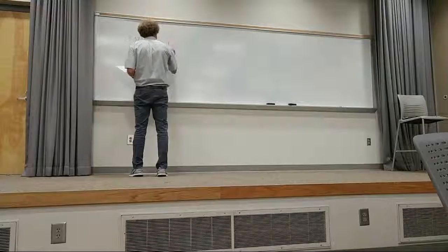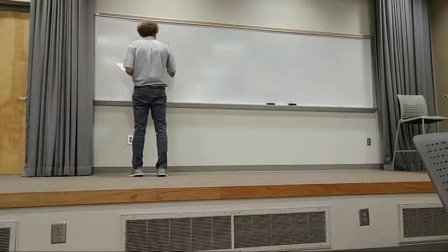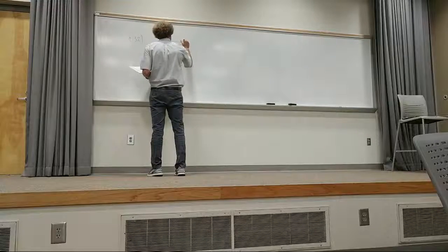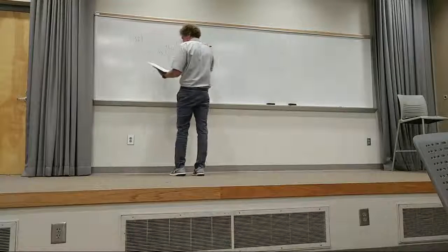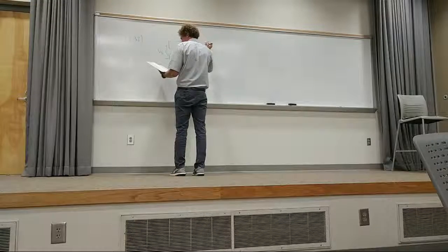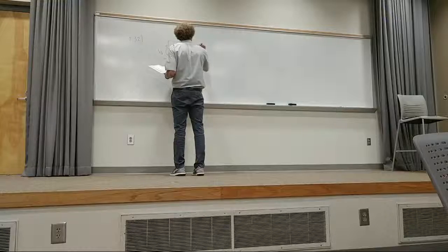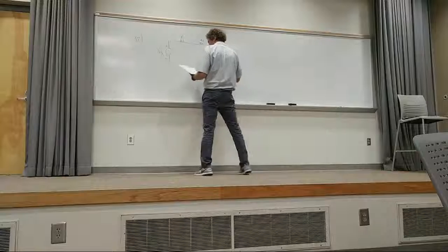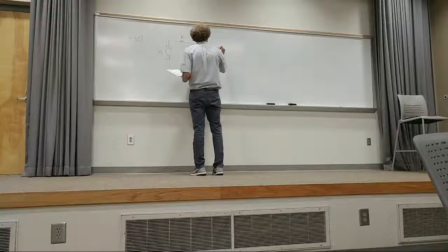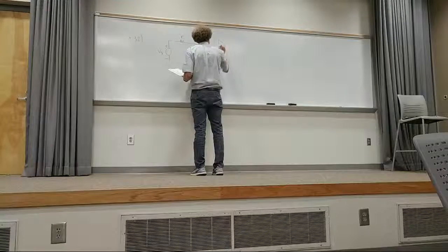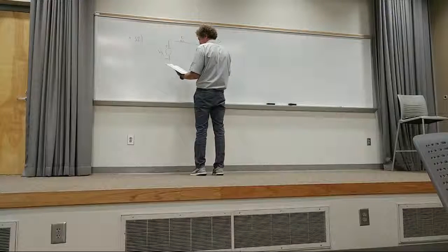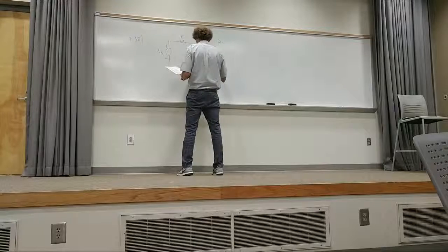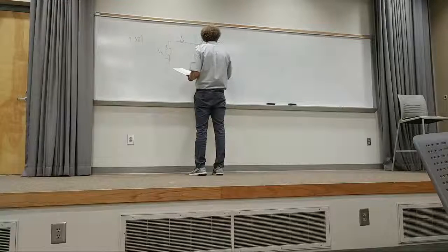Here, we have a voltage. This is VS, the source voltage. Comes through R1. Then through R2. Then it goes into the positive terminal of the operational amplifier. Then there's a capacitor here to ground, and that's C2.